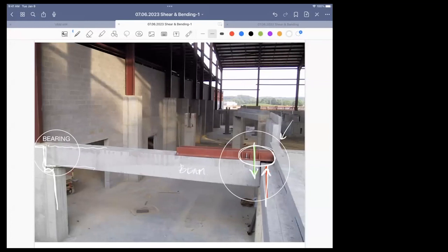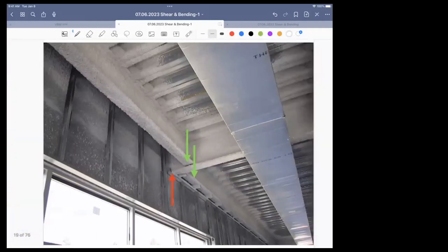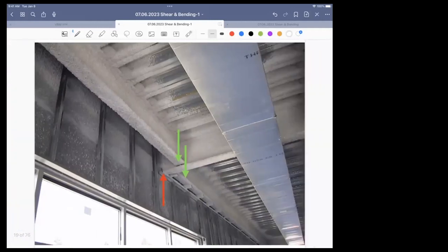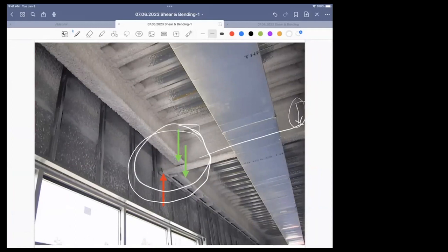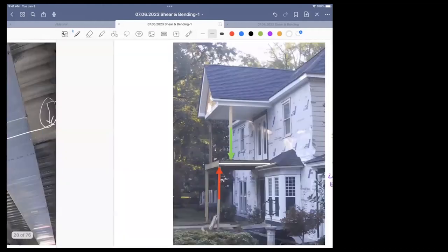Steel is very strong in shear, but these are still 3/4 inch angles and pretty hefty. Anyway, so again, shear is critical at the support. What happens in the middle of this beam is bending and deflection. At the support, where down meets up, shear is critical and shear is maximum always at the support.